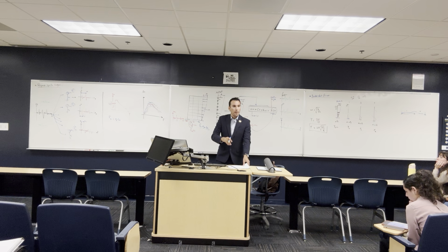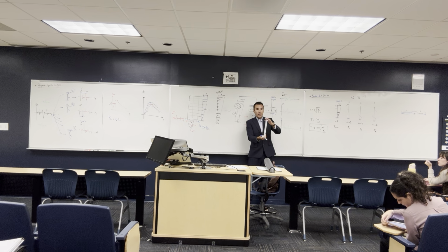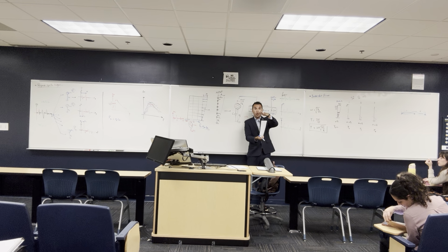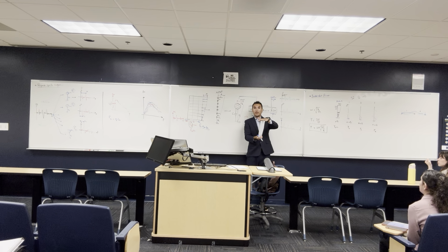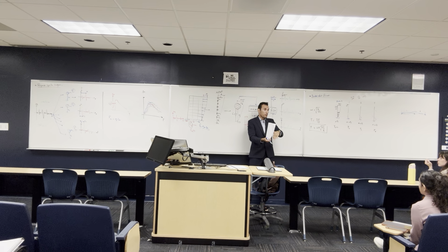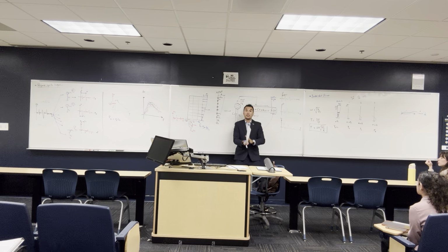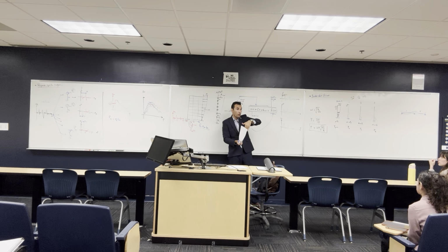Same thing when we design for earthquakes. If the building is not exposed to earthquakes and all the loads are vertical, everything can be compression. You don't have to put that much reinforcement in the columns because there's no bending moment. Everything is going to be compression. There's no way this structure is going to go to the sky. Everything is going to go down.